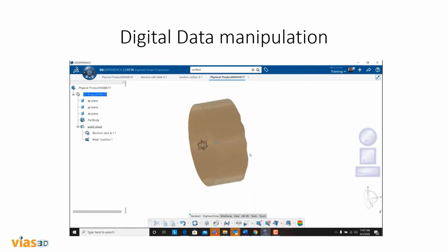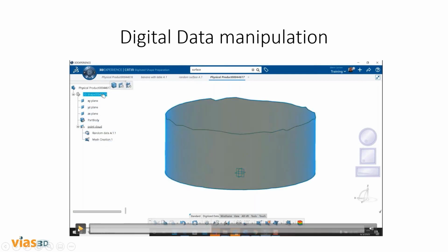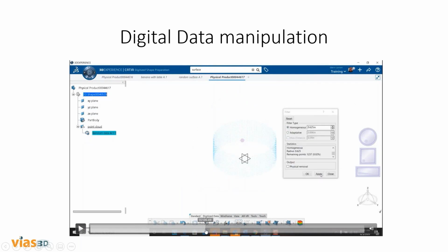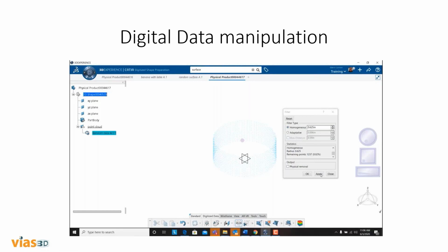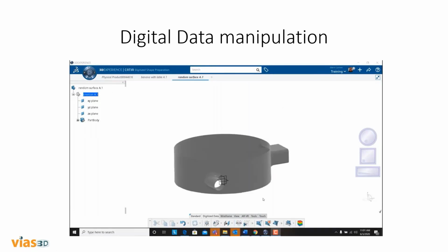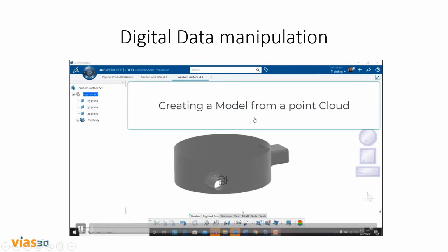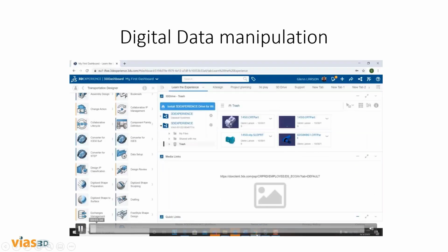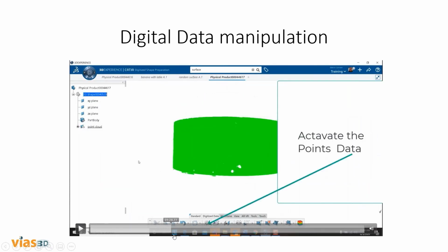So now I'm going to stop the video there real quick. Just to back it up a little bit, when you come up with this filtering method, there are several different types of filtering methods. For the size of the model and the weight of the points, each time it's not like there's a standard number. You're going to have to play with this to get this right. Too many points makes a really sloppy surface. And with the right amount of points, you'll get a nice tangent surface. So I guess I kind of went too far here. Let me bring it back out to where we are.